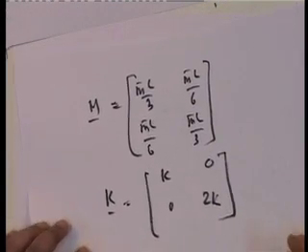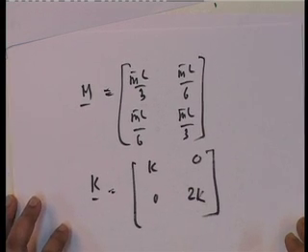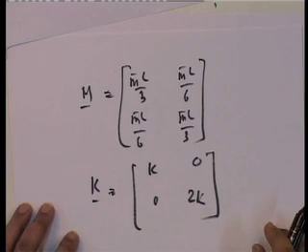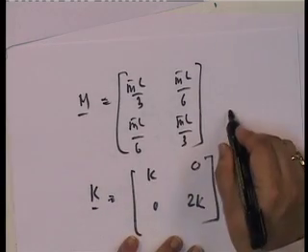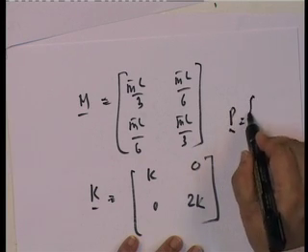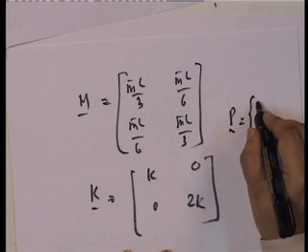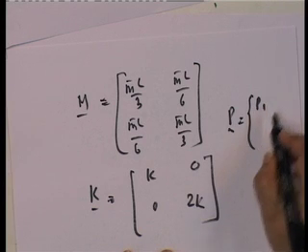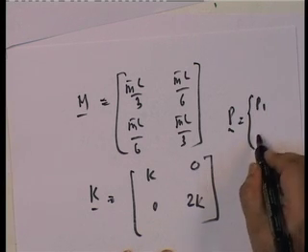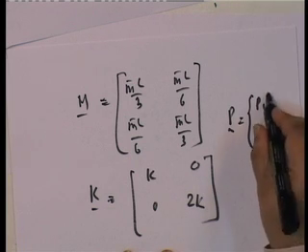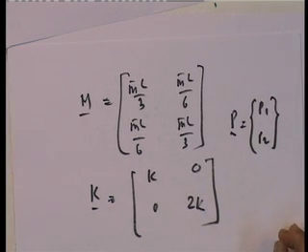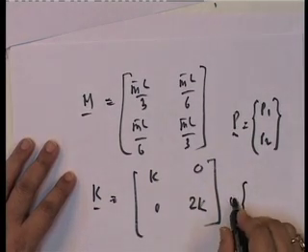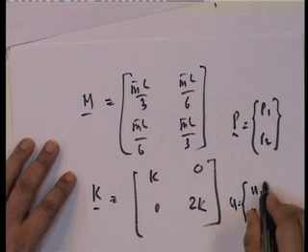Interesting, isn't it? The previous one had the mass matrix uncoupled and the stiffness matrix coupled, and here the mass matrix and stiffness matrix are both uncoupled. And if I look at the p vector, I multiply each one. So, in one I get p1 into 1 plus p2 into 0, so that is p1, and the other one I get p1 into 0 plus p2 into 1. So, this is my p matrix. And obviously, my u's in this particular case are u1 and u2.